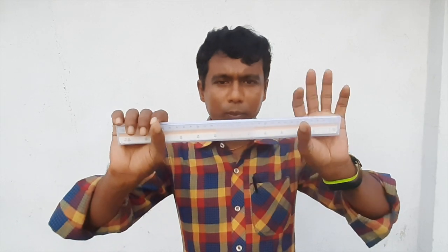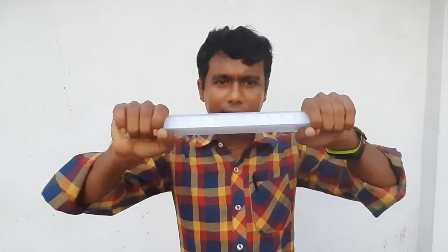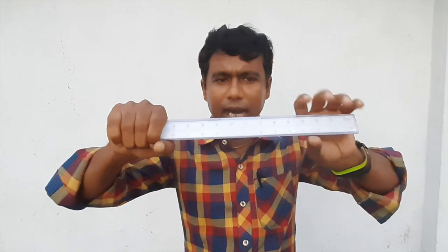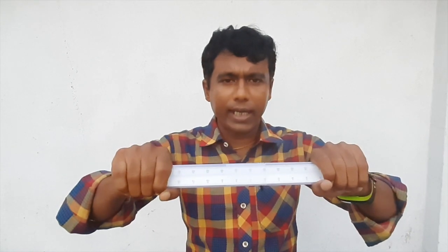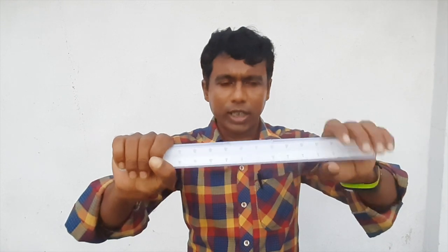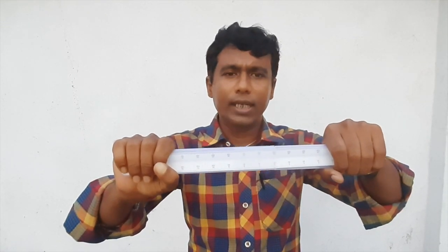That is the torsion. Now, if with both hands we are applying the same directional torque, then there is no angular deformation. But if one end is fixed and the other is given an opposite directional torque, or with both hands I am applying equal and opposite directional torque, one clockwise and another anti-clockwise, then there will be an angular deflection.